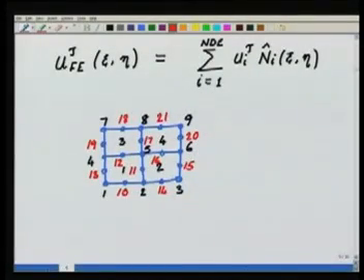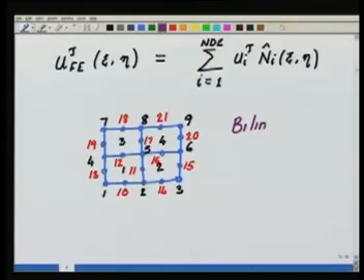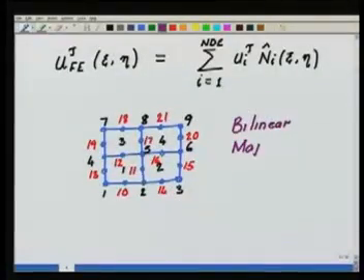And I have deliberately done this kind of numbering so that I first number the corner degrees of freedom. The reason being that, as far as the mapping of the geometry is concerned, the geometry is always mapped using the bilinear map. It does not matter whether I am using the tensor product family or the serendipity family, I am always using the bilinear map for the geometry. That is, I started off with a polygonal domain, so that all edges of all the elements are straight edges.